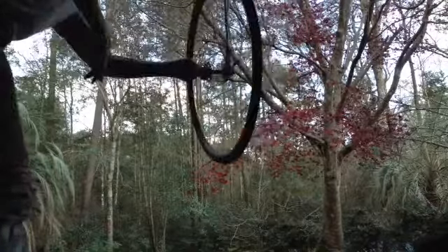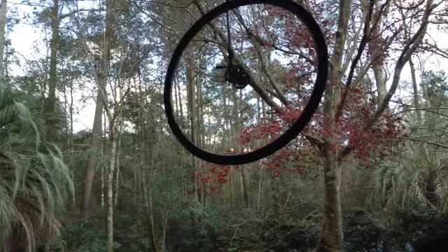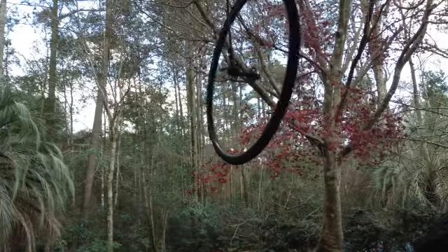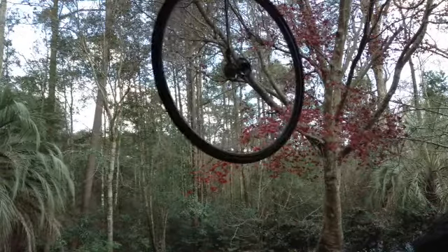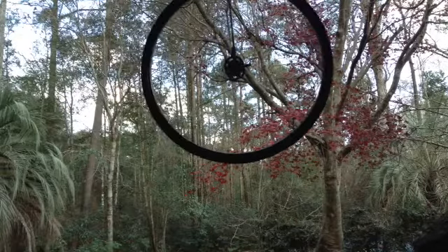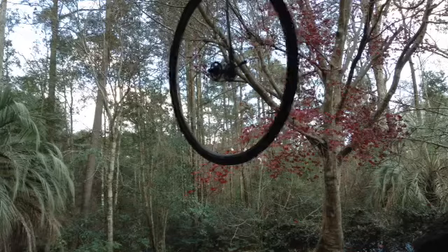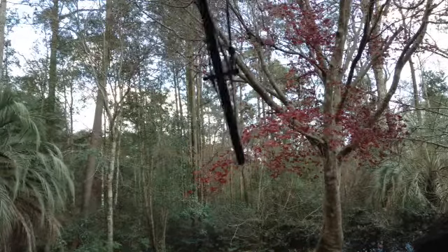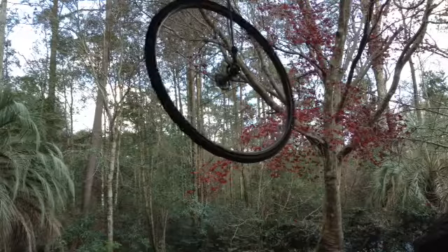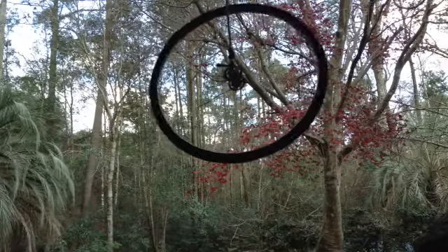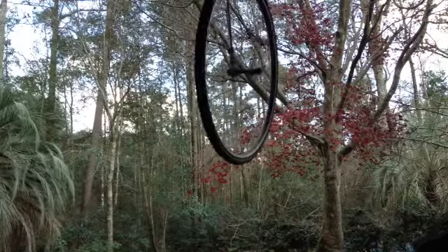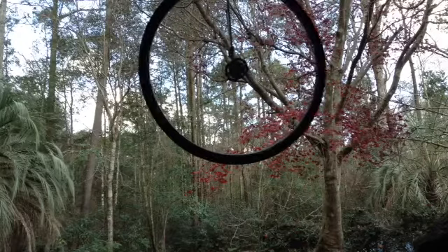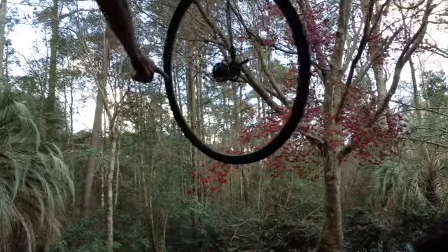So, 1000, 1001, 1002, 1003... about 14 seconds it takes to precess 1/2 of a revolution. So about 28 seconds is what it would do for a whole one at that initial speed. So it's precessing a little faster than we figured it would, which means our radius of gyration may not be all the way out to there, it may only be to there.